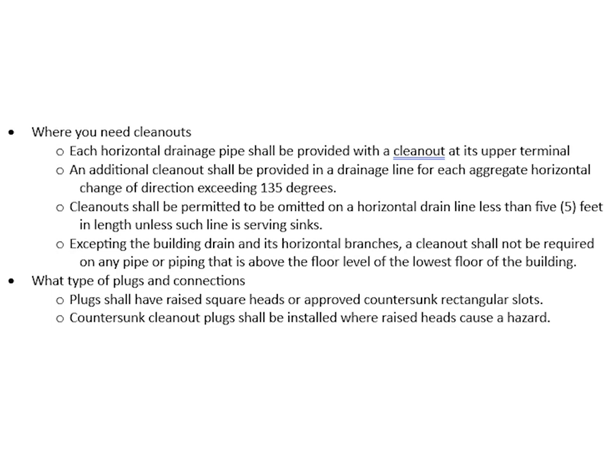What type of plugs and connections on the cleanouts? Plugs shall have raised square heads or approved countersunk rectangular slots. Countersunk cleanout plugs shall be installed where raised heads cause a hazard.